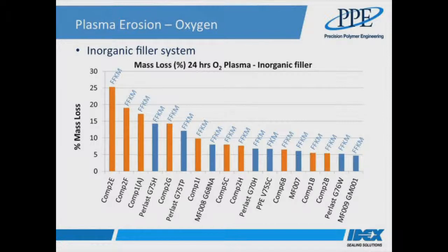So now we don't know the detailed filler systems in all the grades, and there can well be combinations of different filler systems used. However, we can conclude that not all fillers are created equal when it comes to resisting oxygen plasma degradation, and the material that came out best in this trial is actually another development grade and uses a nanofiller material that has been carefully compounded to improve the dispersion of that filler.